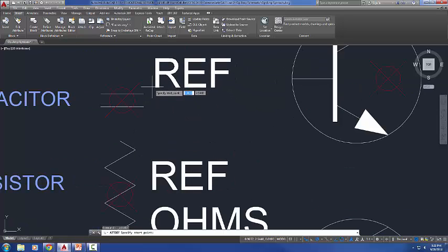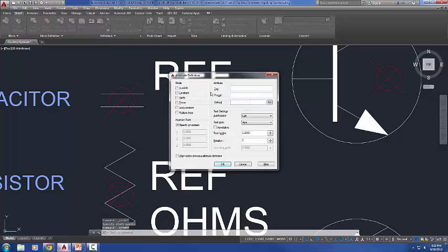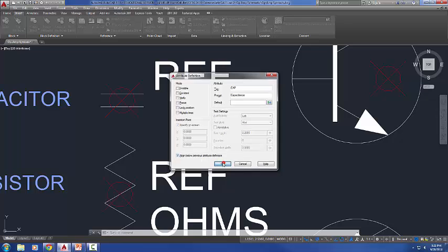It's a little tricky because it's so tiny, but we have two lines of text to put here. I'm going to go to the right View tab, and I'm going to create a 3-point UCS. What this is going to do is allow me to reorient. It says new origin, so I'll leave the default, then direction, and my screen will rotate with it.